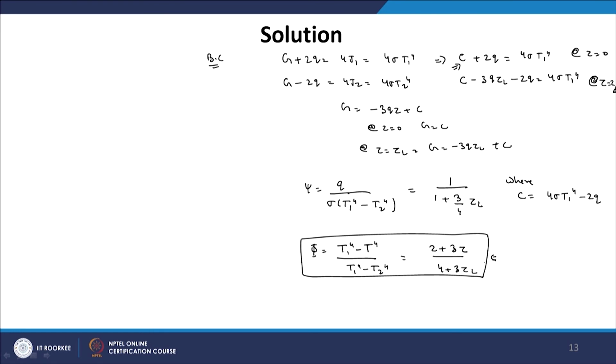So, we have basically calculated in this lecture the radiative heat flux and non-dimensional temperature distribution between two parallel plates using two different methods, the method of Schuster-Schwarzschild two flux approximation and the method of Milne-Eddington, the differential approximation, and the results that we have already shown before in an image show that the method of two flux is relatively more accurate for optically thick cases than the method of differential approximation.